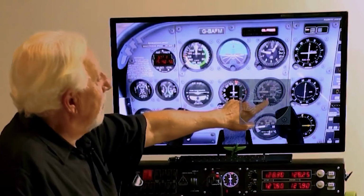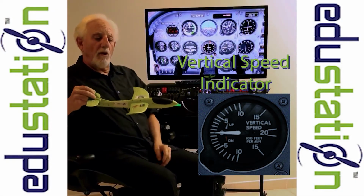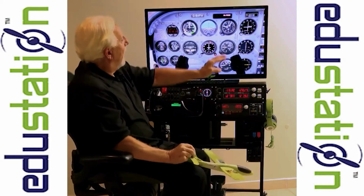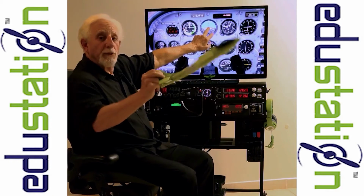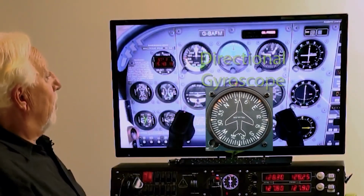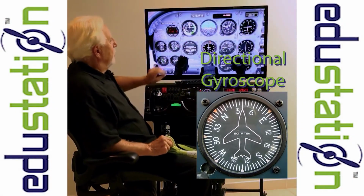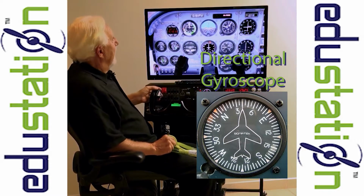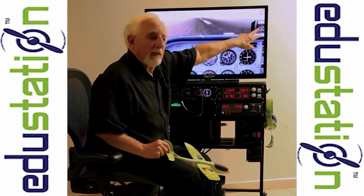The indicator below that is called a vertical speed indicator, and that's telling us in hundreds of feet a minute how quickly we're going up or going down. Our target for learning is 500 feet a minute, which will be about 10 degrees pitch up. The middle instrument is called a directional gyroscope. This is a gyroscopic instrument that we calibrate on the runway to the actual heading of the runway. It should agree with the magnetic compass sitting on top of the dashboard.